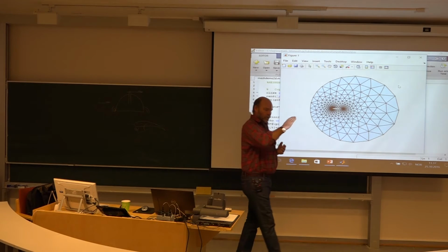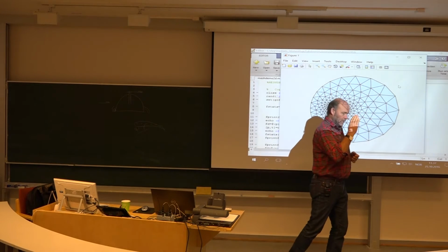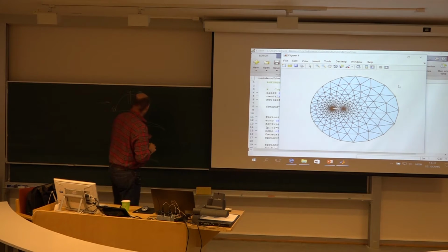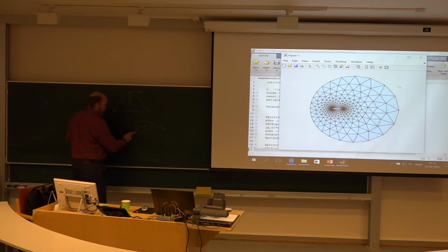Then you want to change the alpha and see the lift and drag coefficients. That's typically what you do with an airfoil. But depending on the alpha, I have my inflow here, and I can construct a mesh and set up an inlet and an outlet. Shouldn't be a problem. But if I want to change the alpha, then I have to change the entire mesh.